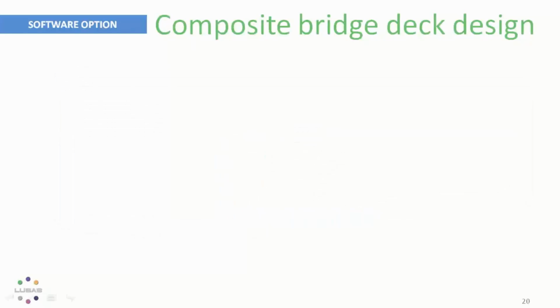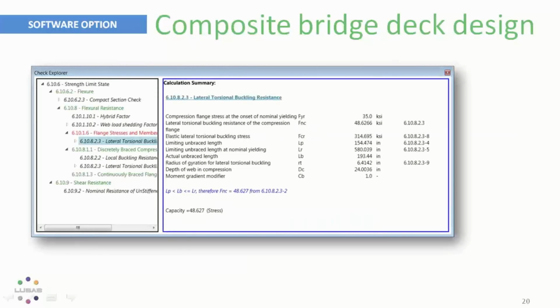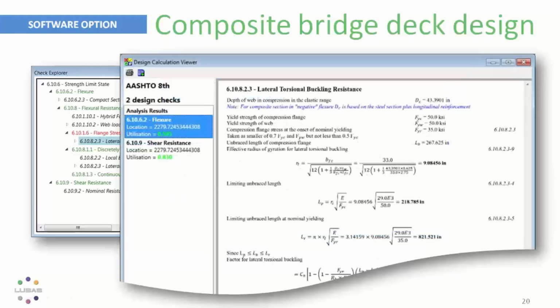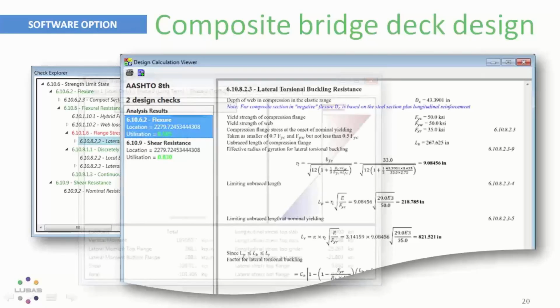With a right click on the row, we're able to see a short form summary of the calculation or a more elaborate blow-by-blow calculation showing all the equations with numbers substituted at each step with each article referenced. Note these calculations can be printed or added to the reporting part of LUSAS, in which case if the model is changed, they will be automatically updated in the report.